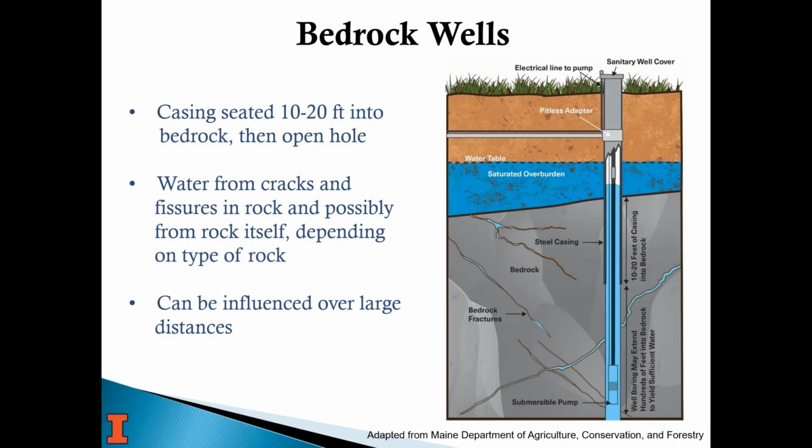And as I mentioned earlier, you typically don't have casing all the way down in a bedrock well because you have to hit those fractures in order to have water. Water just doesn't exist throughout. You have to hit fractures.